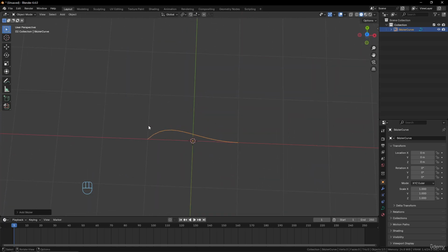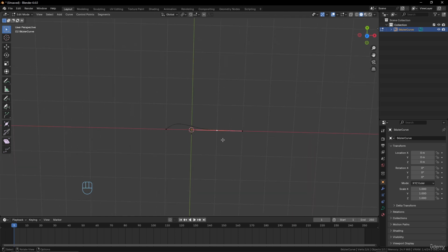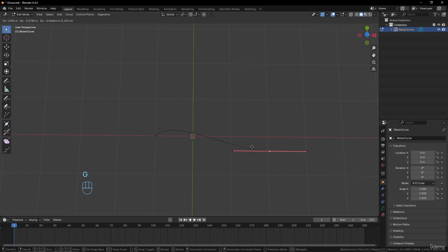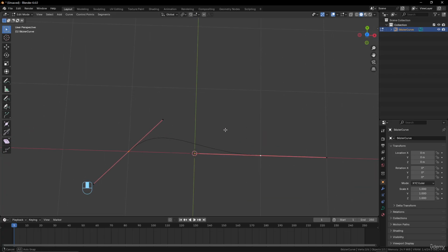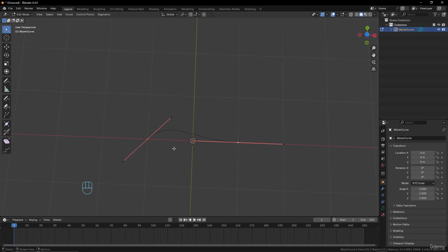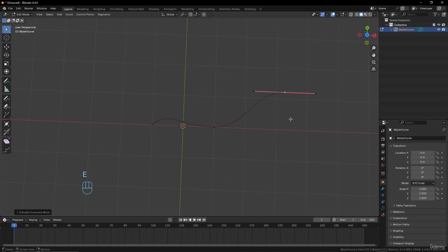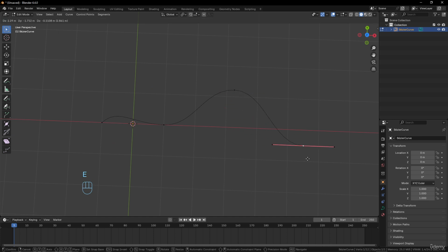And first of all, the Bezier curve here, you can see that now if you go into edit mode, you have here some manipulators, okay? And you can play with them just like that by G, make a rotation as well, or make a scale, and it will change the shape of the curve. So here the Bezier, it's the interpolation between the two manipulators, the two handles, let's call them handles. Okay, so I can extrude a handle like this, and create more curvy things like that.